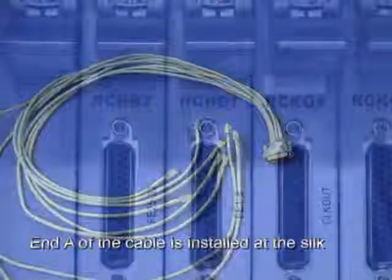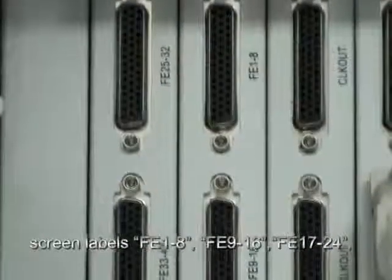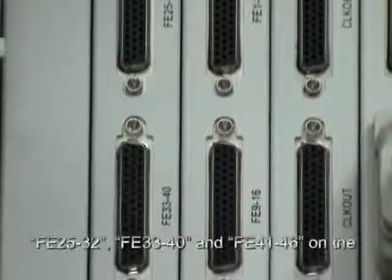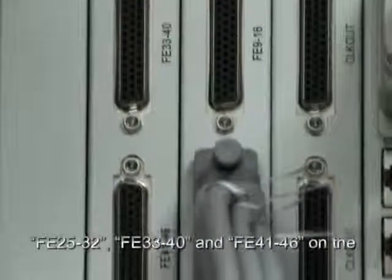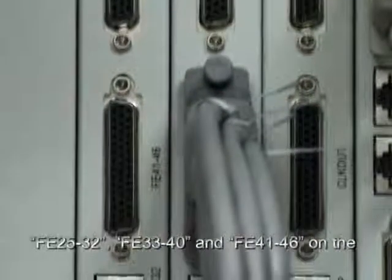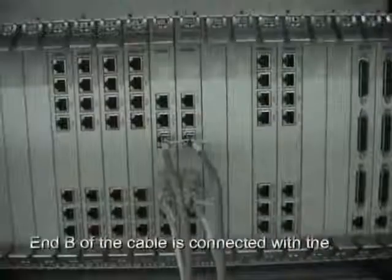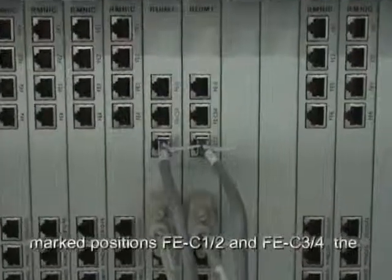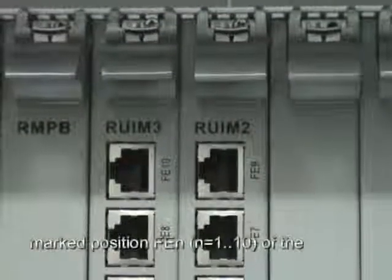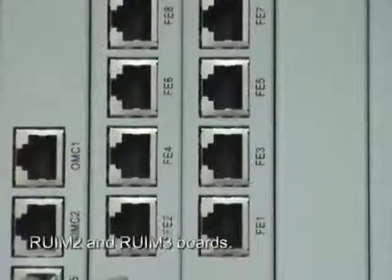End A of the cable is installed at the silkscreen labels FE1-8, FE9-16, FE17-24, FE25-32, FE33-40 and FE41-46 on the backboards RCHB1 and RCHB2. End B of the cable is connected with the marked positions FE-C1/2 and FE-C3/4 of the RUIM1 board, or the marked positions FE1 to 10 of the RUIM2 and RUIM3 boards.